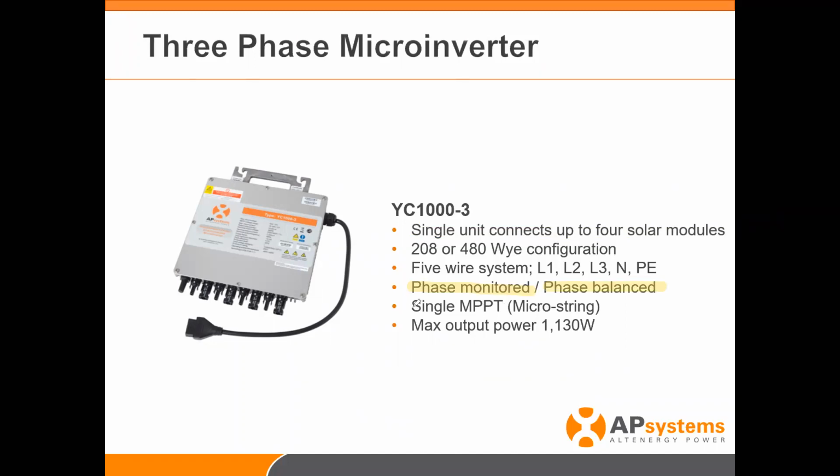As we alluded to in the beginning, single MPPT. So this is a single MPPT. So here, it's the addition of any one of the panels. Again, you can use 1, 2, 3, or all 4 channels. As we get deeper in the presentation, we'll talk more about why you would choose 3 or 4. But basically, it depends on module size.